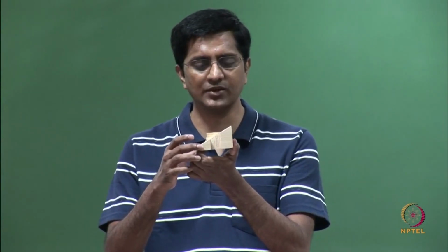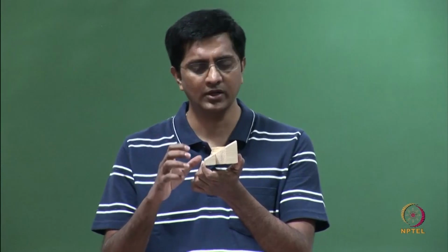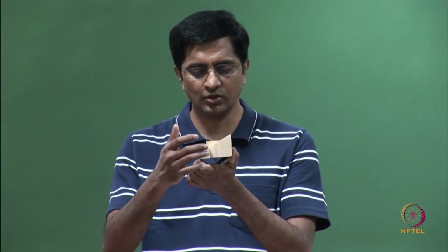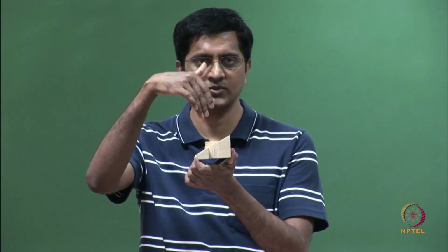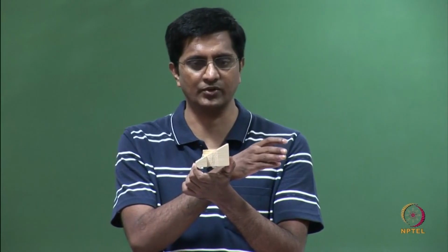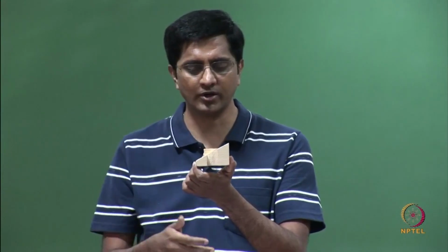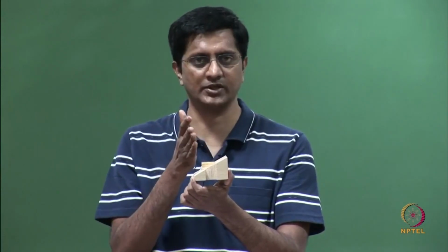Now, if I say that this is the front view, the second question to answer is how many views I need to capture this object. Let us say we capture the front view and the top view, will that be sufficient or not? Sometimes, depending on the number of features, you may want to go for a side view as well, and maybe even one side view is not sufficient, you may want a different side view. Sometimes even none of these basic views like the front, rear, top, bottom and the left hand side views might be sufficient. Sometimes you may have to section this object or maybe you may have to look at it from a different angle.